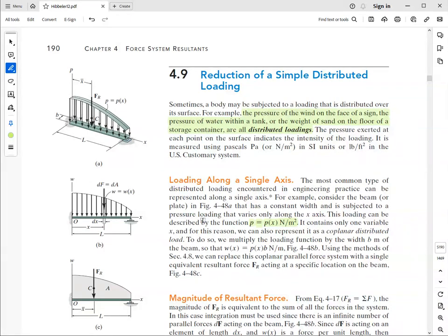Okay, so we want to get the equivalent force of these distributed forces, and assuming that they are given as smooth functions, it would just be a matter of integration. Again, this is force per unit length, force per millimeter or per inch, and it's given as a function. This appears to be a parabolic distribution.